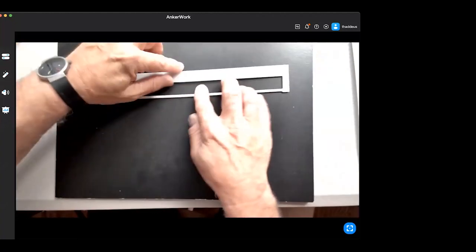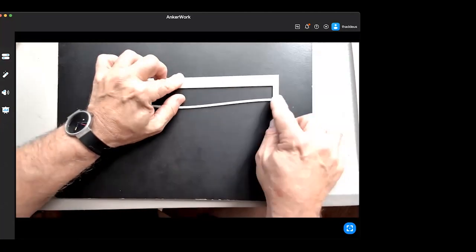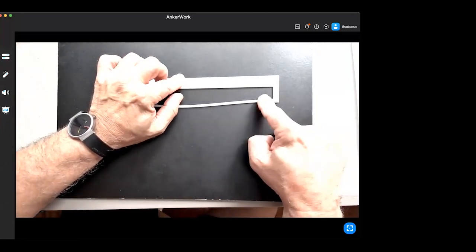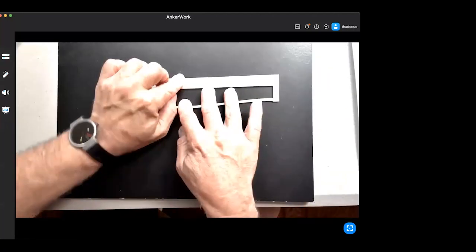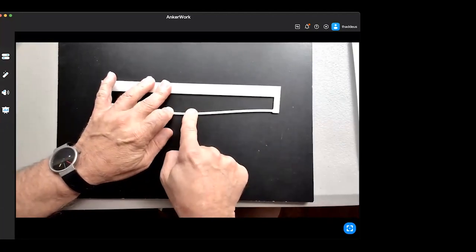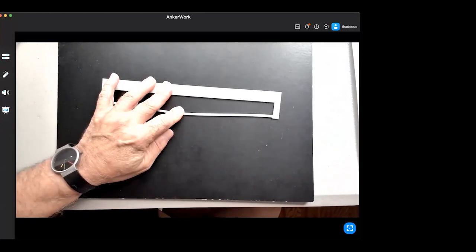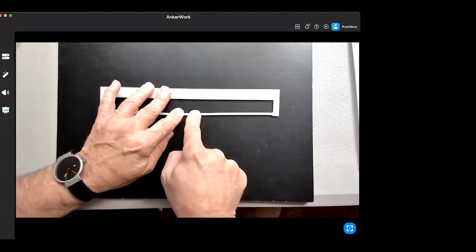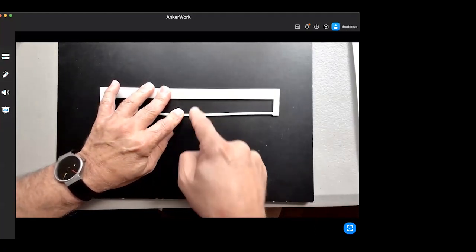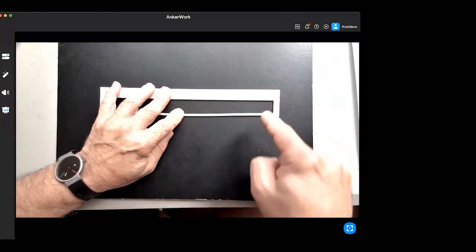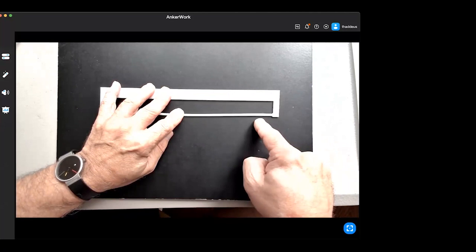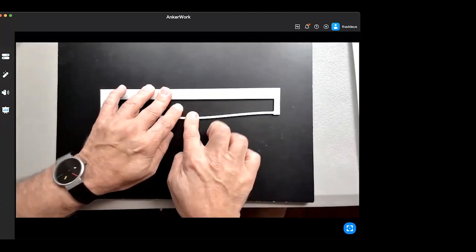No. What this is saying is this remains square. The moment here is negative because the top is in tension, the bottom is in compression. It's the moment. It's not the deflection. Over here, the moment is positive because compression on the top, tension on the bottom. It's reversing here, which is tension on the top, compression on the bottom. Got it. So that makes perfect sense.